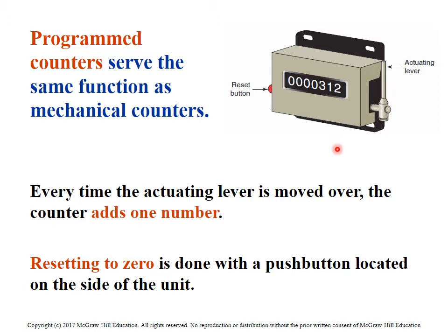Well, you need to know from a tool wear perspective how many hits have been hit on that die, and this type of counter works really well for that. So every time that die closes, it would increment that count by 1.